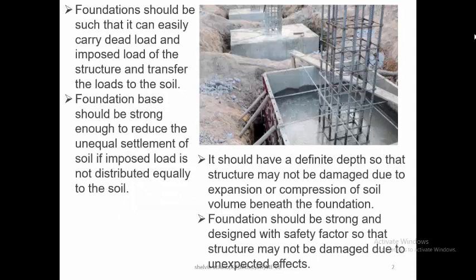Foundation should be such that it can easily carry dead load and imposed load of the structure and transfer load of the soil. Same with what we have discussed in the first characteristic. Then foundation base should be strong enough to reduce the unequal settlement of the soil if imposed load is not distributed equally to the soil.